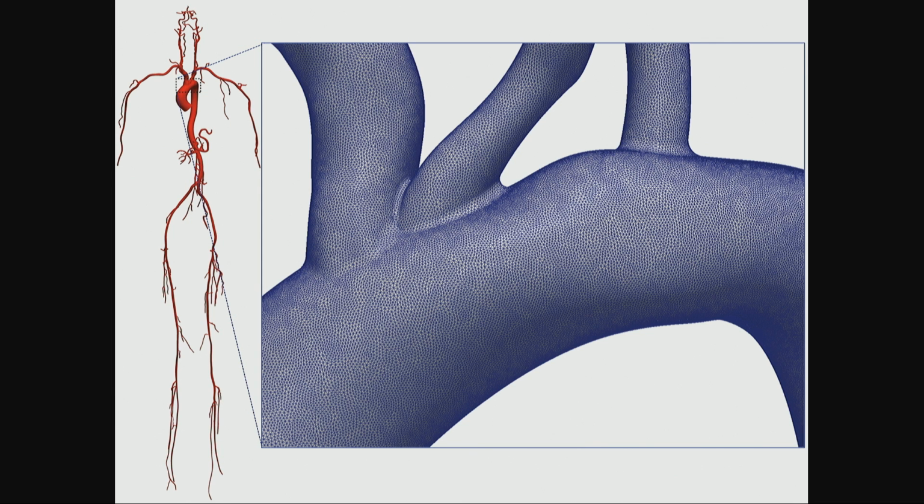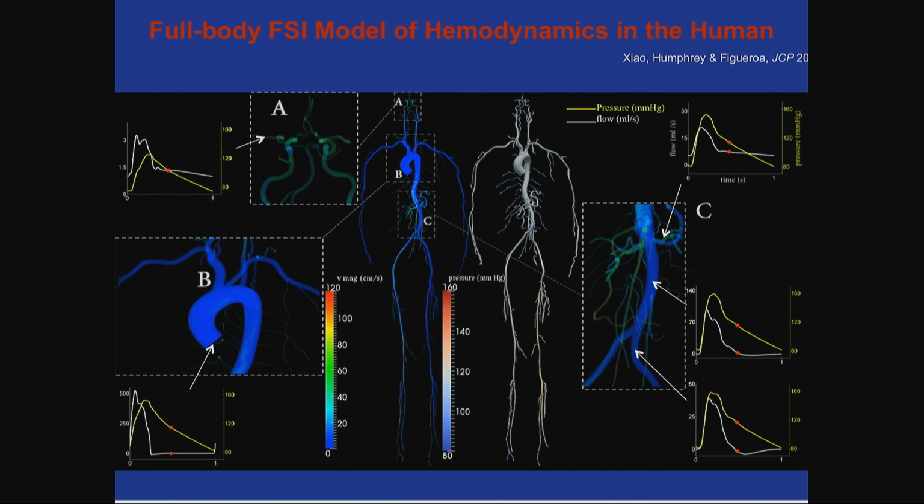And this is kind of giving you the idea of the resolution of the mesh. This would be the surface mesh, your shell in essence. And inside there's a tetrahedral mesh of a similar refinement. So you're actually computing detailed flow features as well. And this is just an animation. You can see the arteries are moving. You have the velocities and the pressure distribution.